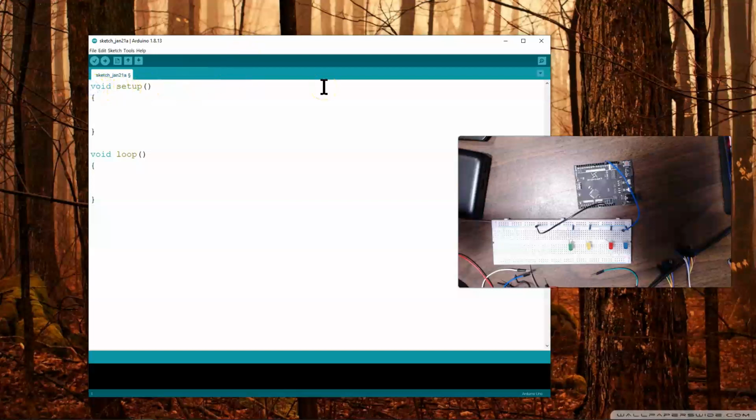Now, when working with the pins, as I said, I suggest that you start making constants in the beginning to keep track of what you have connected to a pin, so what pin it's on, and you give it a good name that describes what it's connected to. Just makes it easier between the code. So, const int LED_1. So that's the first LED.